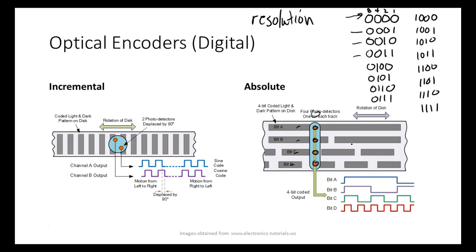The other, more widely used encoder, because of its cost, is what we call an incremental encoder. All this does is give us pulses, and each pulse represents a position. So we put two optical sensors over here. We can't show it, which is why I wanted to bring the other one, because I can't change directions on the one on the manufacturing line. But each one of these pulses would represent a position.